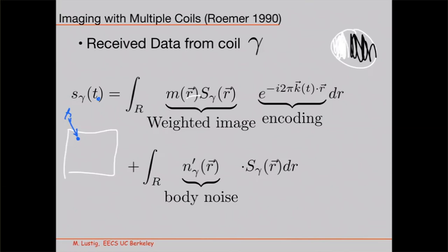Should be Gaussian, right? Yeah, it's bivariate Gaussian. It's an IQ measurement, so in phase and quadrature, bivariate Gaussian. So every sample, you can characterize it pretty much by its variance, because the real and imaginary parts are independent. Okay, so now what happens when you have multiple channels?